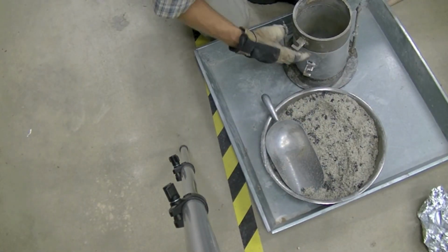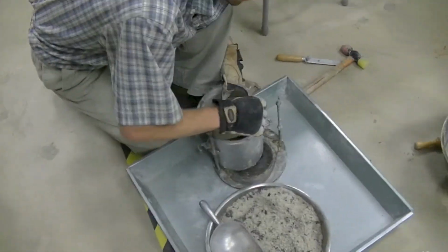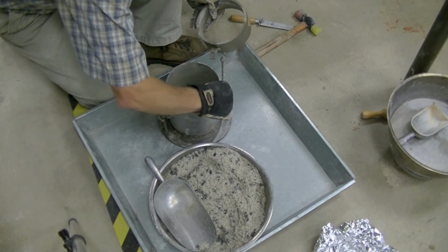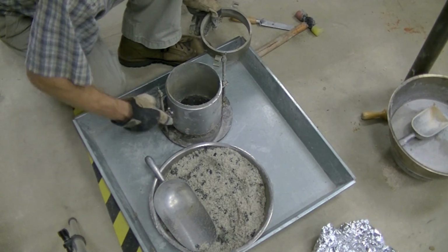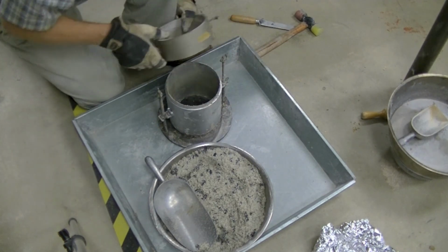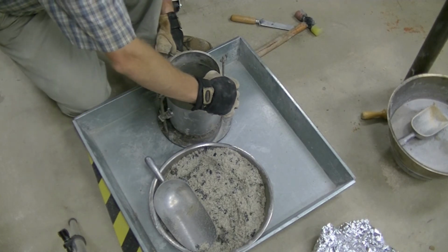Here's an aggregate-based coarse sample. It is considered crusher run or crushed aggregate. This type of material is mainly used directly beneath large-scale roadways with an asphalt or concrete covering. Here method C will be used since the gradation requirement for method B was not met and approximately 23% of the material by mass was retained on the 3/4 sieve.